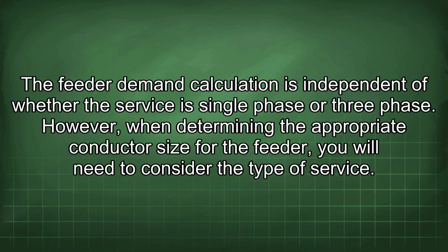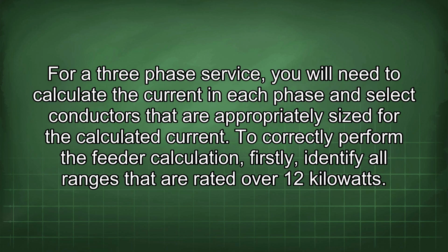However, when determining the appropriate conductor size for the feeder, you will need to consider the type of service. For a three-phase service, you will need to calculate the current in each phase and select conductors that are appropriately sized for the calculated current.